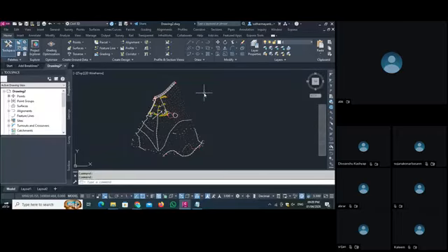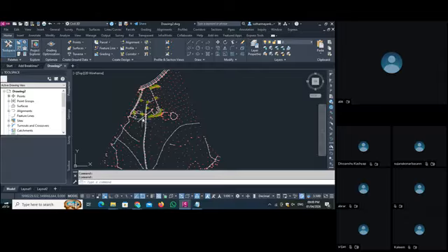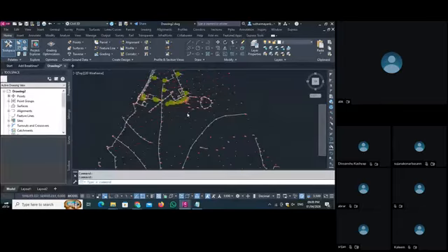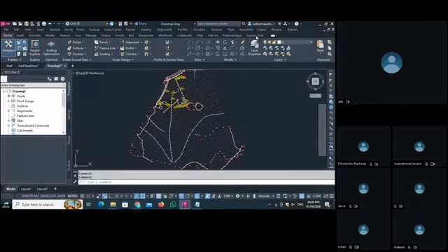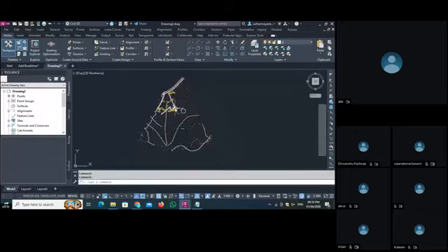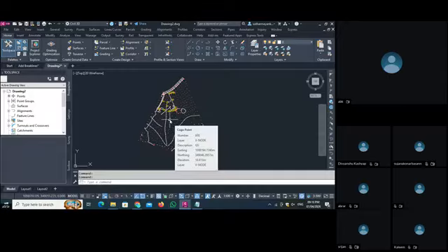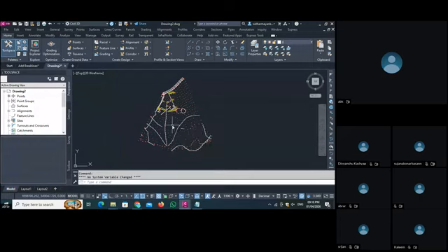Some problems arise due to these small mistakes, because we are working for understanding the workflow. Here we cannot see a geolocation, so our zones and units are also not set here. So that is one issue that will happen. The second thing is the file type is the issue. The third thing is if you do not properly scale them, that is also one issue. So this will happen sometimes.